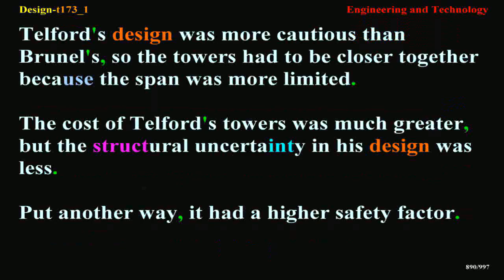Telford's design was more cautious than Brunel's, so the towers had to be closer together because the span was more limited. The cost of Telford's towers was much greater, but the structural uncertainty in this design was less. Put another way, it had a higher safety factor.